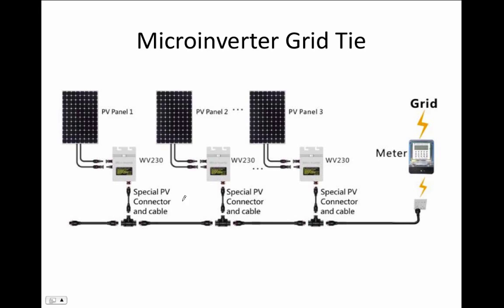It's AC power at this point. Another advantage with these systems is that since each solar panel has an inverter, and these inverters are fairly sophisticated devices, these inverters can report on whether that panel is working and how much energy it's putting out. And on your smartphone, you can actually get a report that tells you how every panel in your system did.